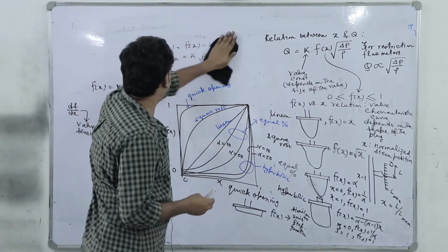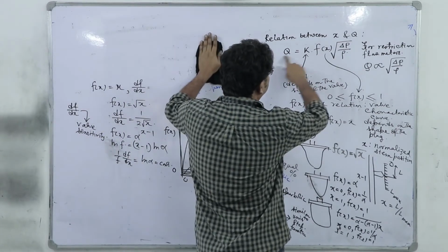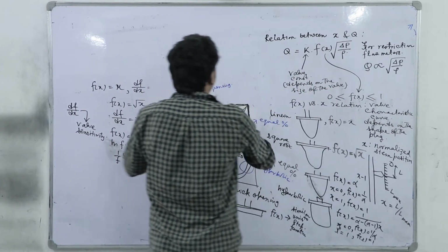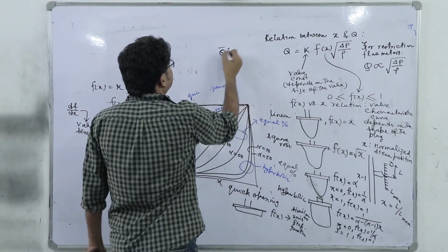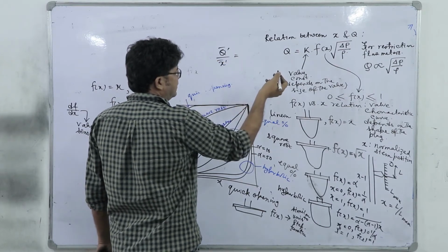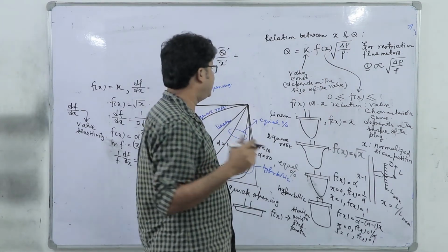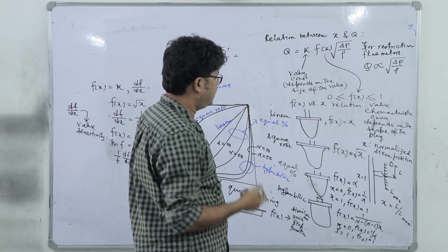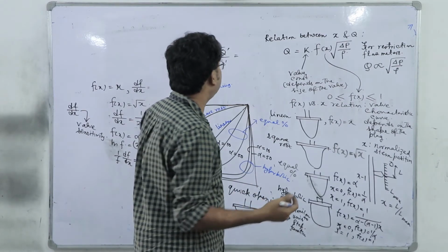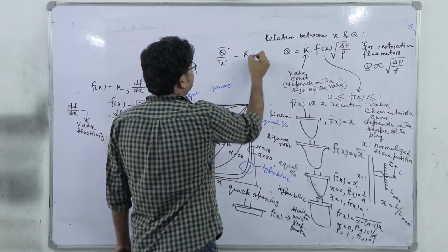So with that understanding, you see that this involves no time element. If I write the transfer function after linearization maybe, only in the case of a linear valve we don't have to linearize, but if it is equal percentage, square root, or hyperbolic, we have to linearize, and finally we can group everything as KV.